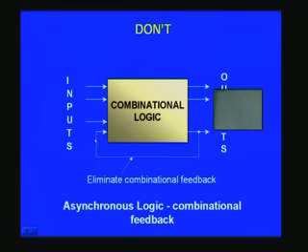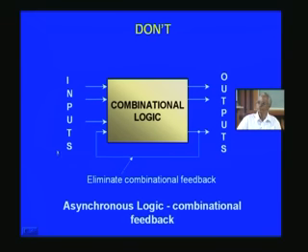For example, if you apply a 0 at the input here, and the combinational logic might produce a 1 here, and then 1 being fed back, it keeps on rapidly switching from one state to another, and this will be uncontrollable, and thereby it will not work in the ultimate chip that you have designed. Furthermore, this may be rejected at the synthesis level itself.